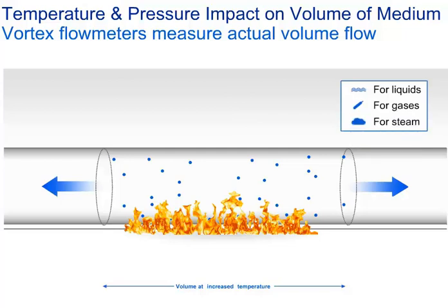For steam, depending on the type of steam, with temperature compensation only for saturated steam, or with temperature and pressure compensation for overheated steam. Modern vortex meters with enhanced computing capability can calculate the energy flow directly from all of this information.